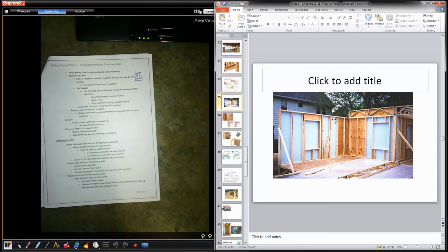Where this wall here is going to have all the joists sitting on top of it, so that's going to have some weight there. But again, you can see 2 foot on center, single plates, you've got foam on the outside. Okay. So plywood in the corners to stiffen up. So that's 1 long wall, 1 sheet of plywood. Takes care of that wall. Usually a rule of thumb is 1 lateral support for every 20 feet of wall.